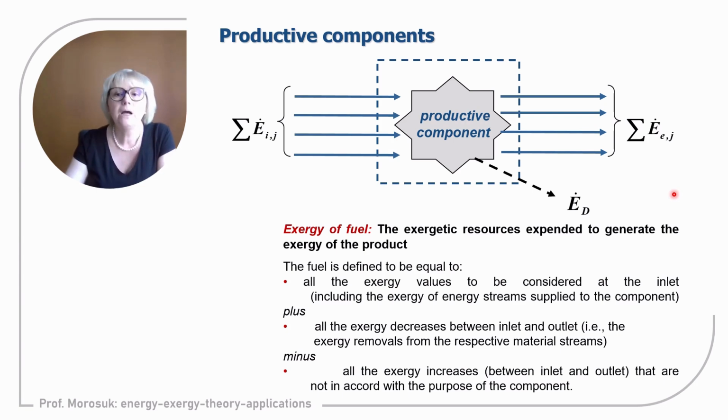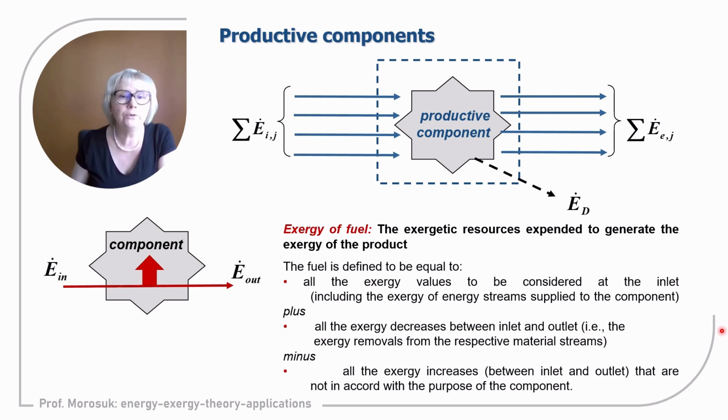We have an official definition of exergy of fuel, which is given on this slide. It is possible to follow this definition, but believe me, it is quite difficult to apply, particularly when you have a complex component with many streams. I will give you a very simple explanation of what fuel means. We need to consider each stream, each material stream or energy stream, going through the component.